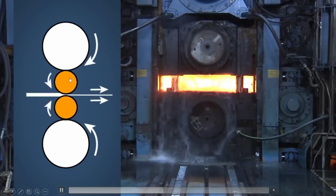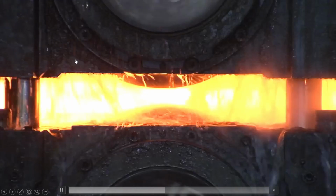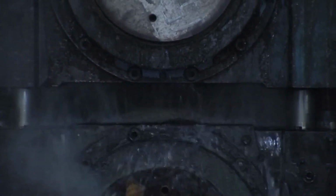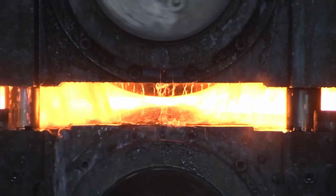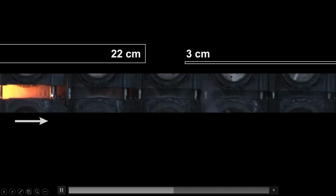Here you can see there are two rolling mills which are reducing the thickness. You can see there are two more mills on the top and the bottom, so they are applying even more force. When the slab is very strong and very thick, you need to apply even more force, and then you can reduce the thickness. You just saw the material go forward and then it reversed back.